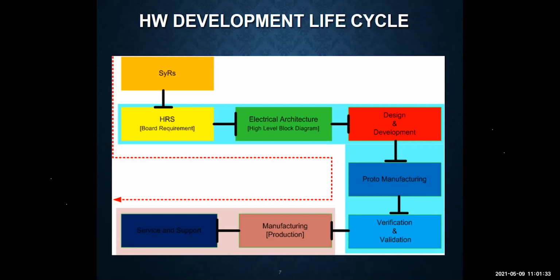And then further coming to the design, here is where you get into the low level design, like what kind of sensor it is going to be. If it is an ambient sensor, is it just a thermistor or an LDR, a light dependent resistor, or are you going for any new technology? If you are going for a processor, what kind of processor are you going to use? A microprocessor from Texas Instruments, or NXP, or Qualcomm, or Intel?